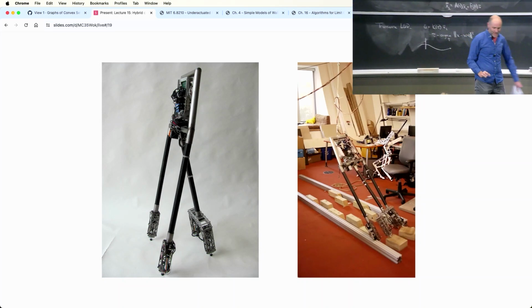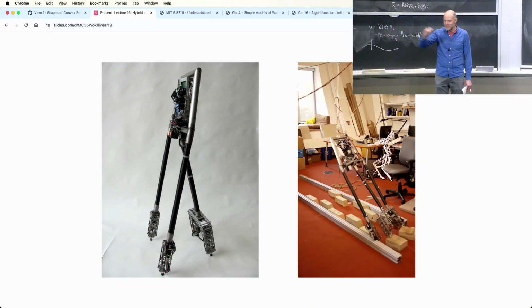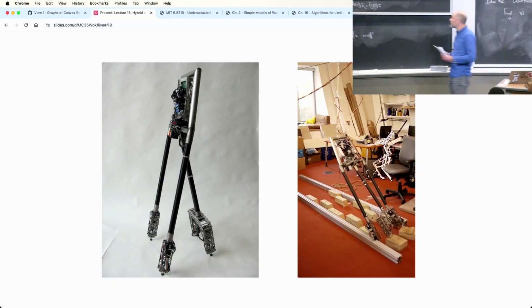Interestingly, for the compass gait, if you try to stabilize it in time, LQR works very badly. The K matrices, the S matrices you get will say that you have very high cost, and the K matrices become very high, because the compass gait does not have enough authority, really, to catch itself up in time. If you solve the transverse LQR, you get beautiful small gain matrices and a controller that runs until your wire runs out.